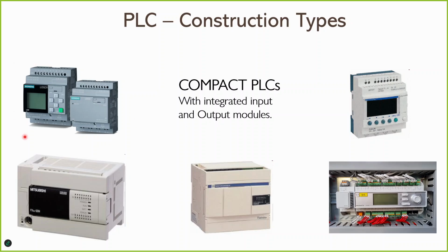Many of you might be familiar with the Siemens LOGO. It's one of the most common PLCs out there. So with these PLCs, you can see directly, I don't know if you can read this clearly, but basically what you see here, this connection point is 24 volt DC. That means you can power it directly from here. You can connect inputs, you can connect outputs. Same with this PLC, same with this, same with this.